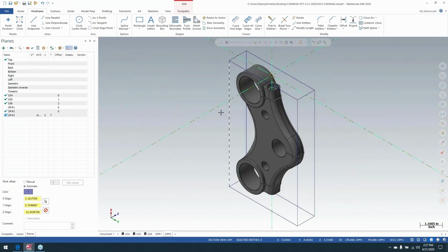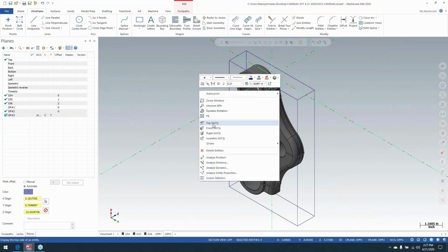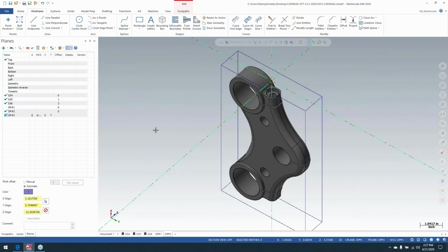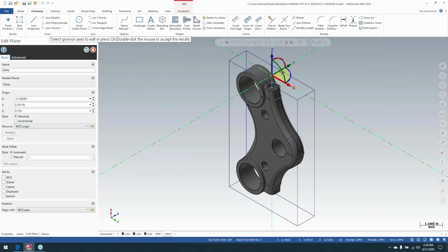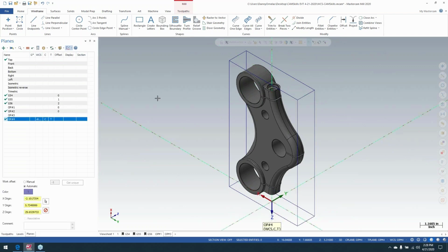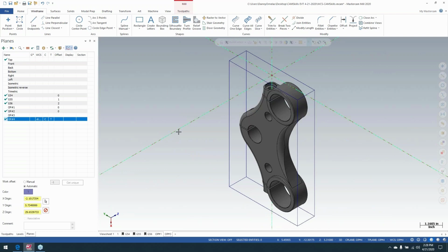So if I put this in a machine, let's say I had a fixture, you would set it up like that. Then again, you continue on, flip it over for the other side. You could manipulate that as well. Take this guy, duplicate him, rename him. Edit him. And then move him down again. And again, this is using the CAD tools from Mastercam, just putting them into range. Put isometric on that, and it would flip that part over like that.